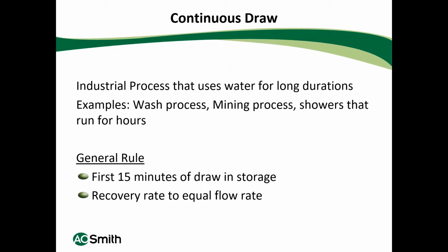Continuous draws are a little bit different. A good example: I was just in a facility where they wash eggs all day long. The eggs go down conveyors, and a spray of tepid water washes them continuously for hours on end. That is how we would size that. For continuous draws, the first 15 minutes of the use would be in storage, and then the recovery rate has to equal the flow rate of your hot water. So first 15 minutes of water in storage, and then if you're using 100 gallons an hour, you need a water heater that's going to produce 100 gallons an hour.